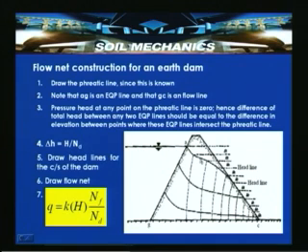So, this topmost line, by the procedure which was discussed, is going to yield this particular line, which is the phreatic surface. So, pressure head at any point on the phreatic line is 0, because, being at atmospheric pressure, the pressure head is 0. Hence, the difference of the total head between any two equipotential lines should be equal to the difference in elevation between points where these equipotential lines intersect the phreatic line.